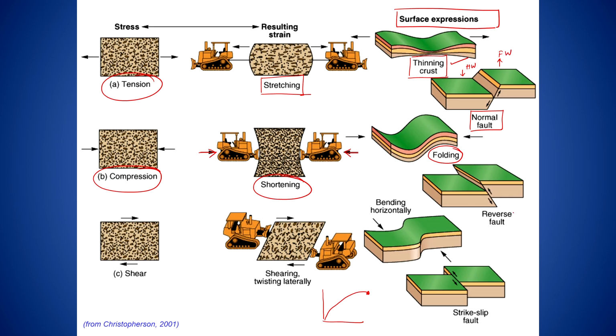In this case, you will enter into reverse faulting, and this is your hanging wall, which is going up, and this will be your foot wall, which is the stationary wall in both cases. Okay. Then the third environment, what we call strike slip, is your shear. Okay, where you shear the crust. So shearing is taking place, and we also had discussion in the previous one that either it will move with a normal component, or it may move up with a reverse component, along the strike.